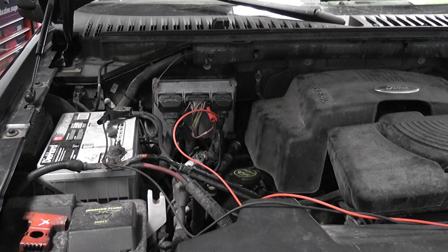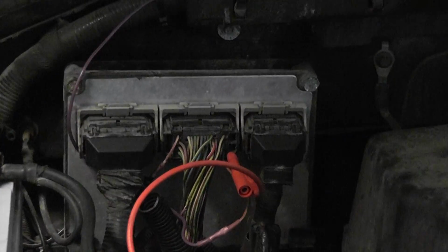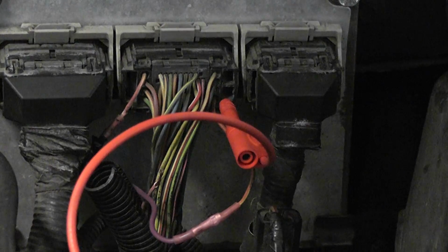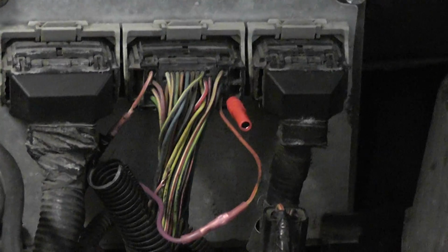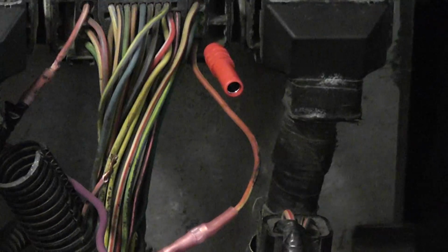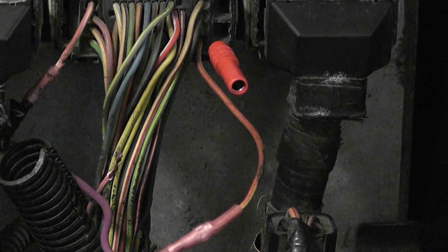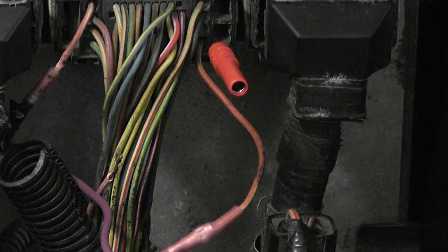Okay, so we're under the hood, and again, we chose this test because of its ease of use. This is a very easy test to use, and we're going right to the computer. And again, somebody's been here, and they already have done some rewiring. And of course, it's the wire that we're testing. Can you pull that clip out of there real quick so I get a shot of that wire? Just pull it. Good. So you can see that somebody has cut this. What's the color of that wire? Orange with a yellow tracer? Yes. Our number 6 control wire is orange with a yellow tracer. Somebody has cut the wire and rerouted a new wire to cylinder number 6.